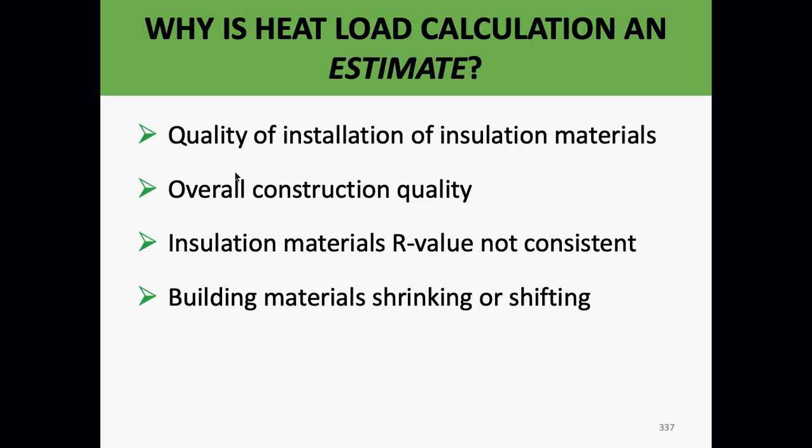Okay, this comes under building materials shrinking and shifting. Remember the bricks the other day of the shifting house? Okay, the house has shifted. All of a sudden I have a heat load problem. Gaps, paths for leakage, unintentional thermal bridges. Okay, we haven't talked about occupant influence, like going in and out, opening windows, changing set points on thermostat, leaving vent fans on. Cooking and baking, an oven puts off a lot of heat. A dryer removes a lot of air.